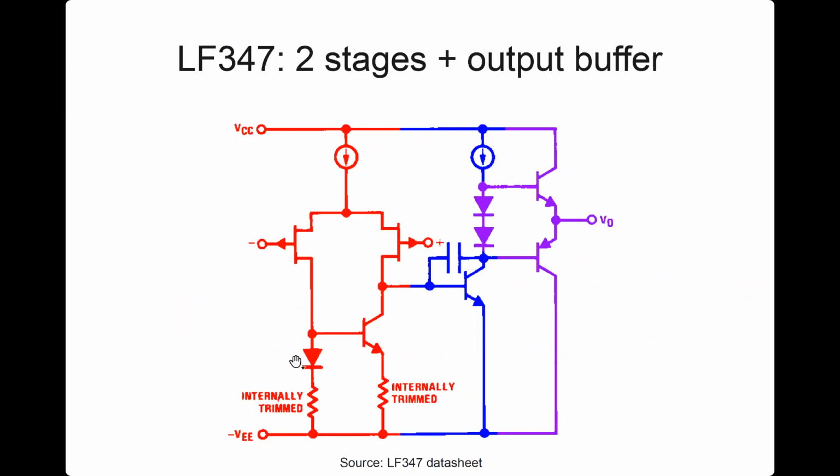The diode connected transistor is shown as a diode. It's really a diode connected transistor, that's all. And this, whatever the symbol is, it's called a junction field effect transistor. Probably you have not encountered it, but you can just think of it as a PMOS depletion mode device. That is PMOS transistor, but with a VTP less than 0. That is, with a VSG of 0, it will be on. That's all. So that's a small difference.